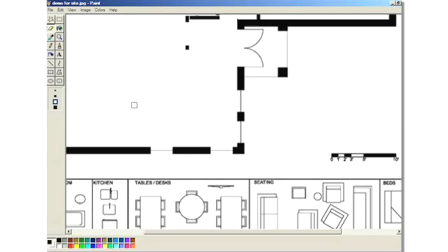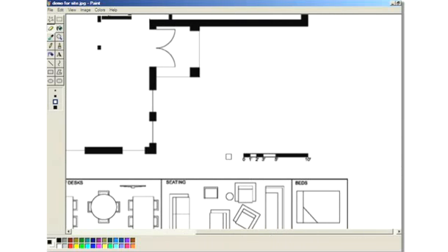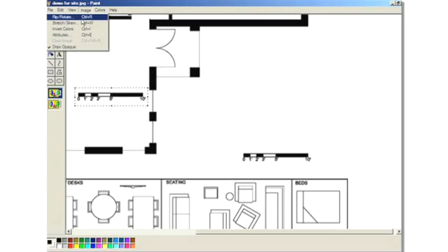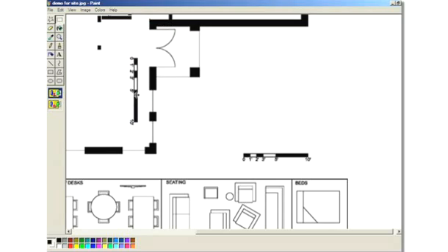Now, these drawings are all to scale, and what you will find over here in the corner is the scale. You can use this in a couple of different ways. One is to use it as a ruler, and so you can copy and paste it, and then take it so that you can see how big something is. You can rotate it 90 degrees, so that then you can see that door opening is actually 6 feet in diameter.